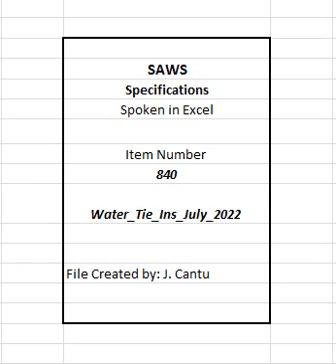2. The opening or closing of SAWS valves smaller than 12 inches can only be performed in the presence of the SAWS inspector. 3. The opening or closing of SAWS valves 12 inches and larger, and any valves identified as critical, for example division valves, can only be operated by the SAWS Distribution and Collection Department.